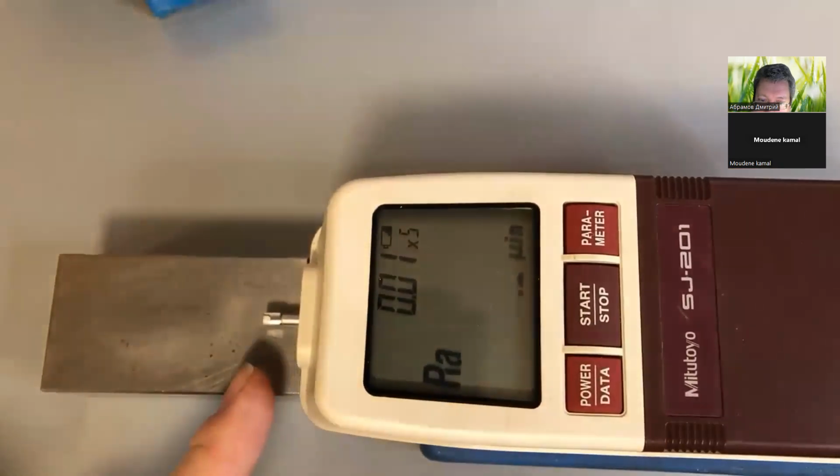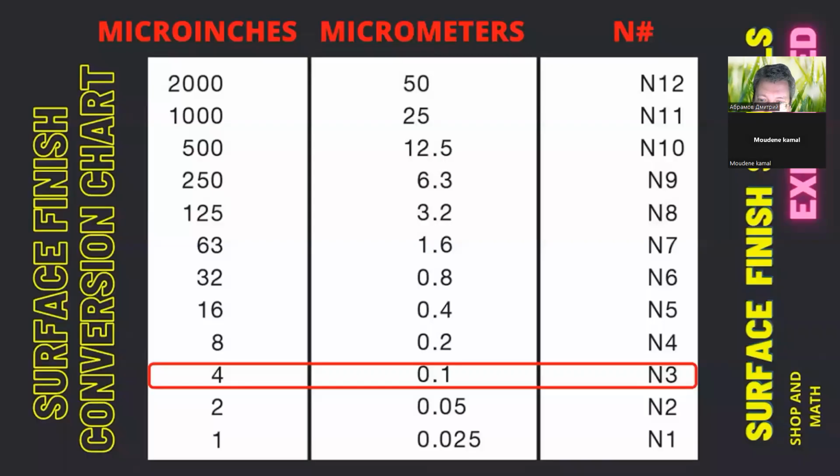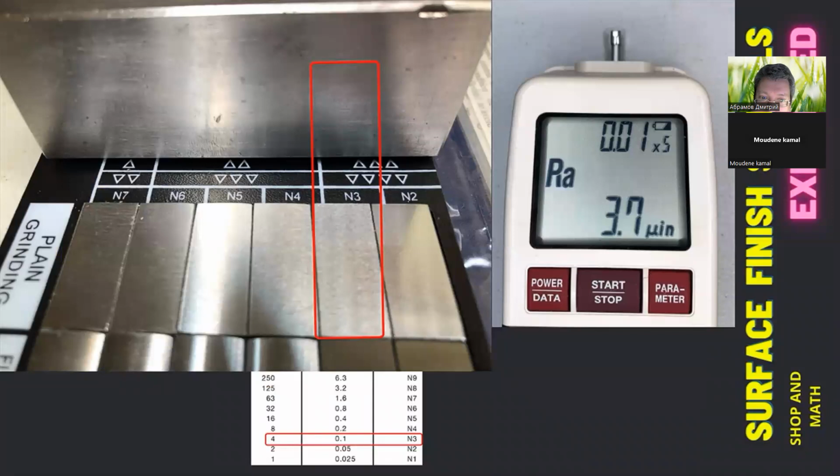You see this guy moving inward, then it's going to move outward. 3.7. Let's look at our conversion chart. 3.7 converts over to a roughness grade of 3. And that looks basically what we have, a number 3 roughness grade.